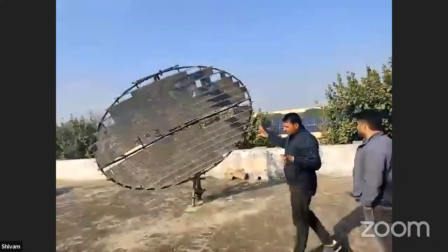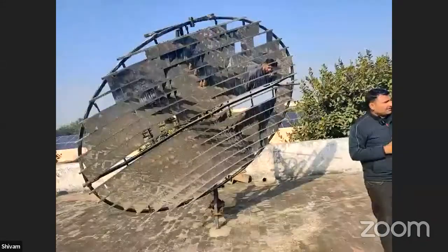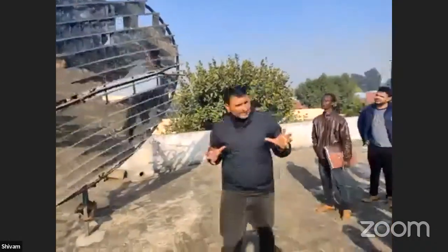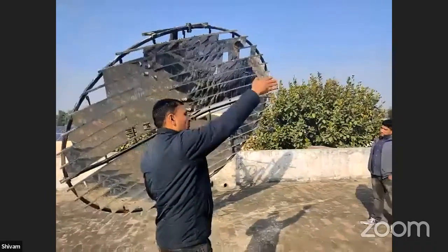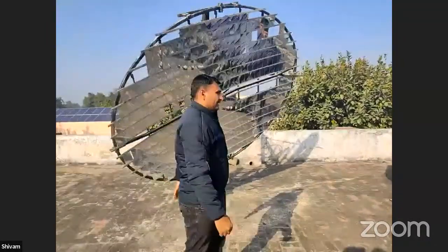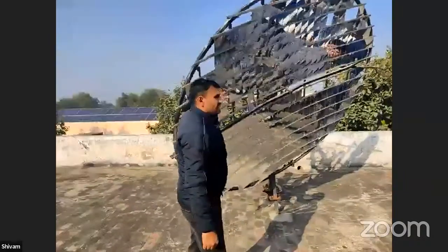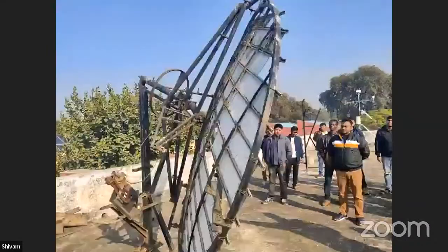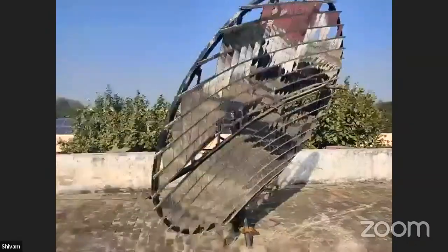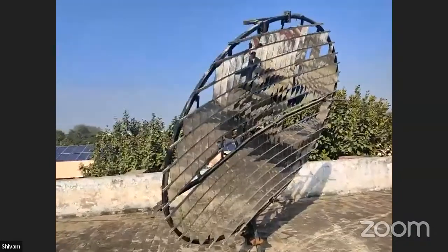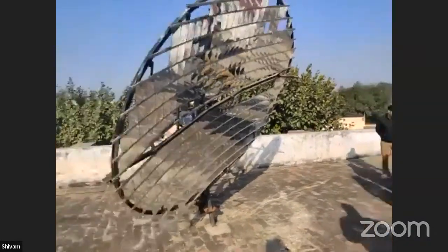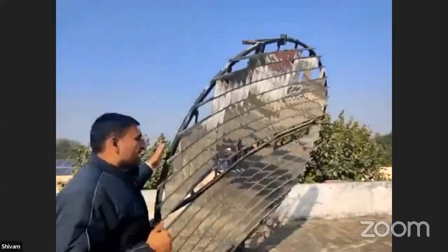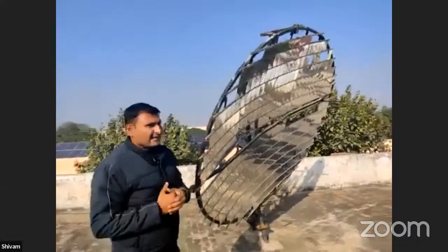This is a concentrated type of collector. It is called a Scheffler reflector. It is one-axis tracking: as the sun moves from east to west, we can track it with a single axis. The radiation incident on this glass reflecting surface is reflected to the focus, at some distance from the reflecting surface. We can use it for water heating, cooking, drying, and various purposes. Our institute won a 3 lakh cash prize on this setup, organized by the ONGC Solar Chulha Challenge.